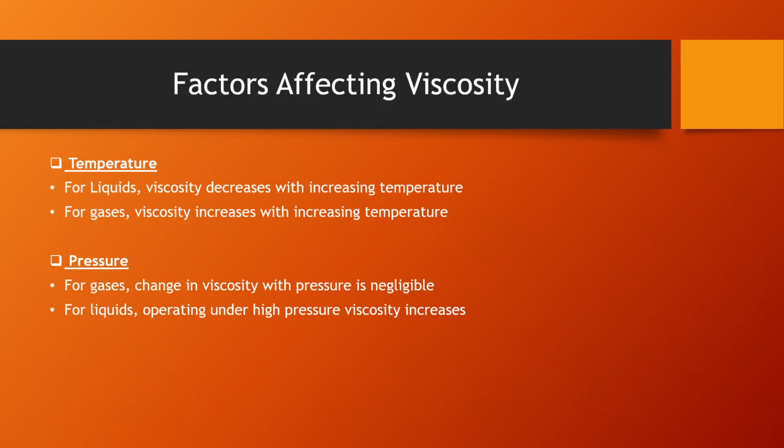Factors affecting viscosity. The major factor that affects viscosity is temperature. You see, in case of liquids, as you increase the temperature, the viscosity will decrease because as you increase temperature, the molecules inside the liquid start to go further and further apart. So the viscosity would decrease.